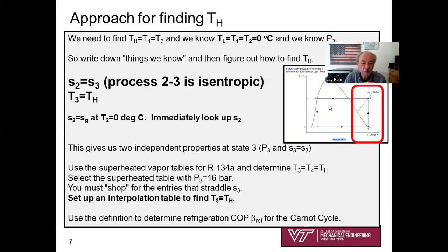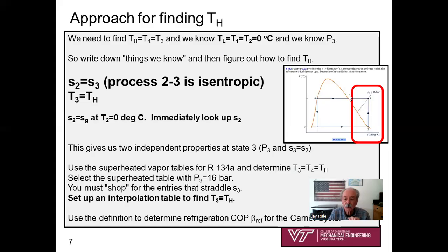All right. So let's draw down what we know. I've got to move my zoom image here. Here's a little thumbnail view of our basic sketch, and let's study on it. For what's given, how can we find T3? That's the key. As we're studying, one thing we know is about process 2 to 3. This is the easiest way. Do you see that state 2 is a saturated vapor? And you know the temperature of T3.